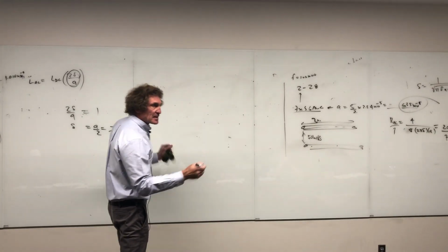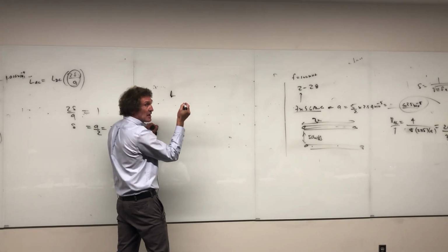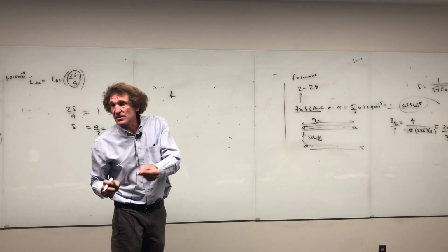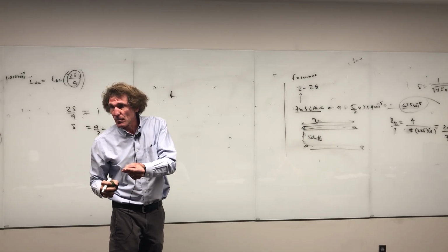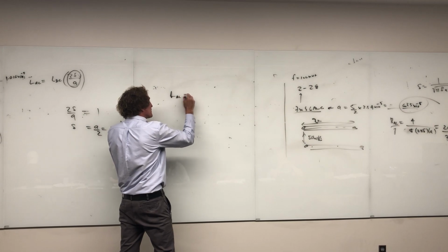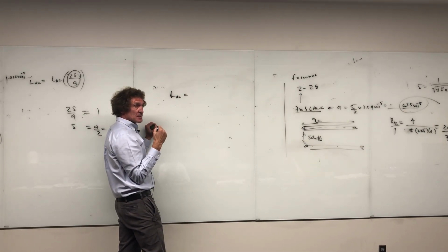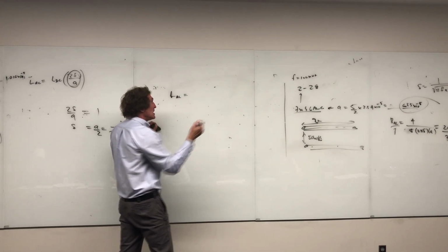But if we're doing the inductance, let's start, first of all, with inductance, and we know we have to use the AC formula. Do you all agree with that? We already know that. So it's going to be LAC per wire. First thing is the length. The length is 2 times the length of one wire because there's return current. Follow me? So it's going to be 4.